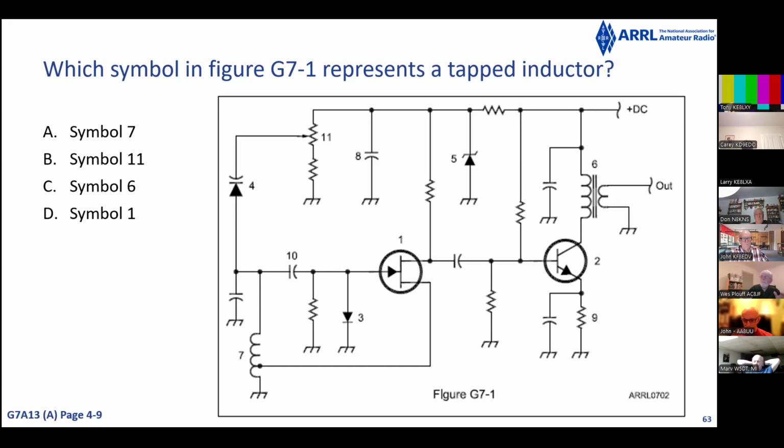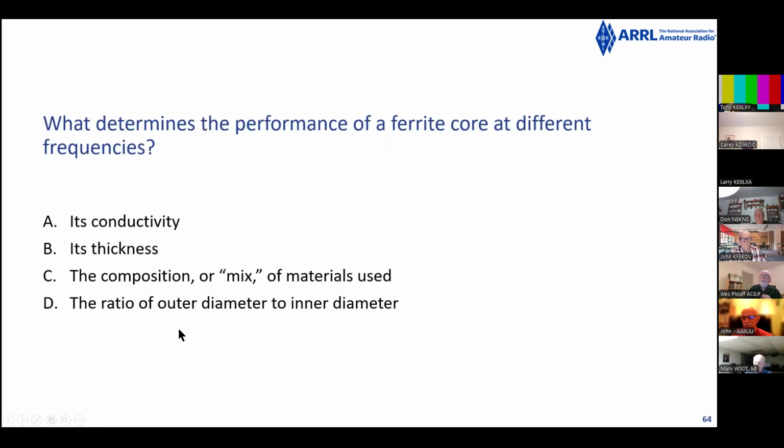And I'm sort of hand waving a little bit here, but there are circumstances where that's perfectly fine if you want to use the transformer property of a coil by tapping in at a certain point. And they call that an auto transformer. Yeah, an auto transformer, that's right. The auto because, instead of 2 windings, the 1 winding acts on itself.